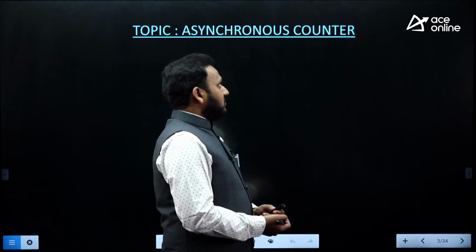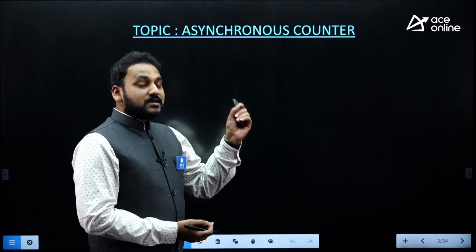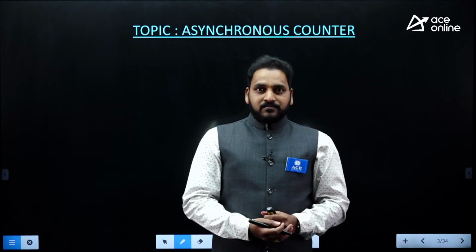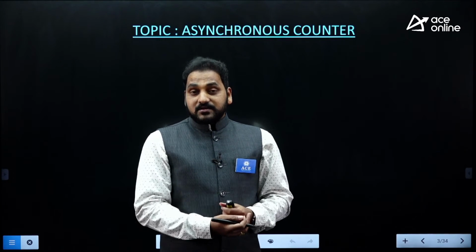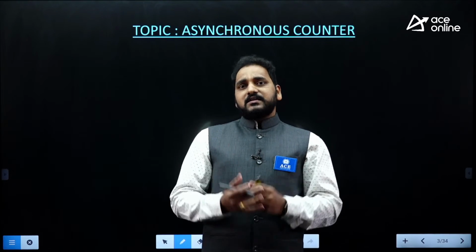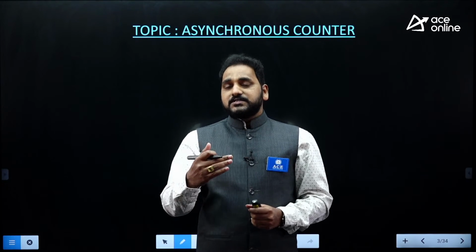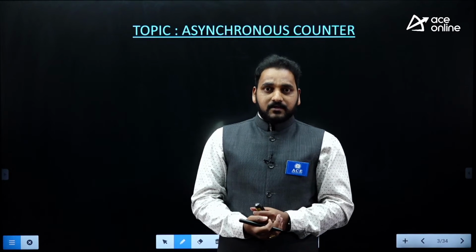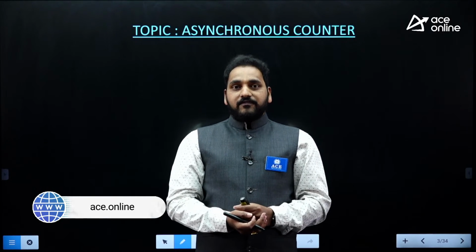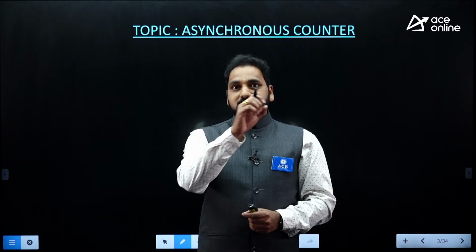The topic I selected is the asynchronous counter, but it is a subtopic of a counter. What is a counter? It is a sequential circuit consisting of n number of flip-flops, with their own interconnections, such that we arrange the flip-flops to get a certain combination of binary, and that binary is nothing but the binary equivalent of the number of clocks given to the counter. That is the thing we can see on the counter.